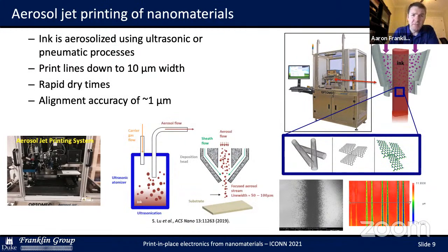For instance, the print nozzle diameter, the aerosol flows of the different gases, and even the mechanism of aerosolization, pneumatic versus ultrasonic, can often give you the ability to print larger constituent particles.